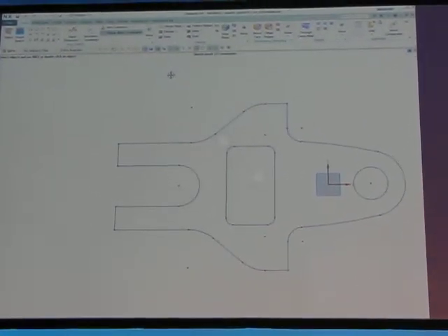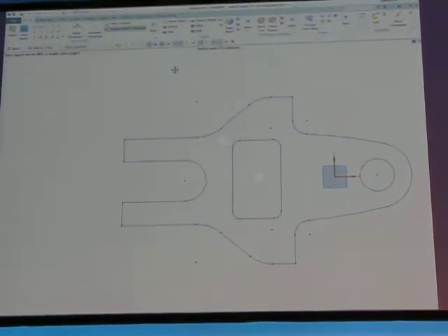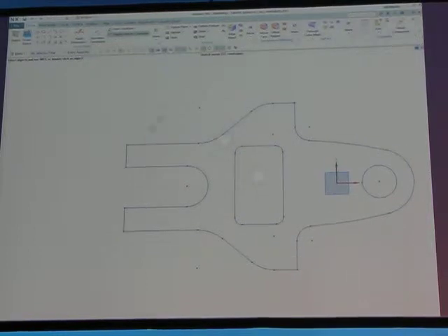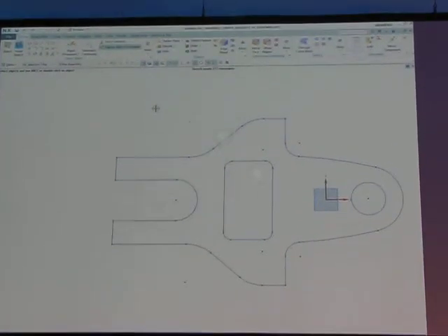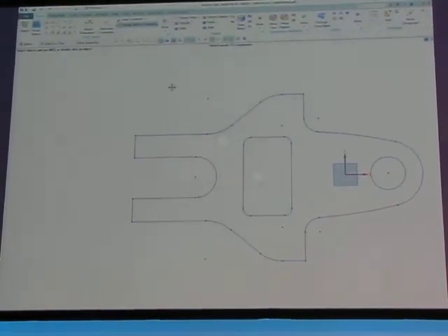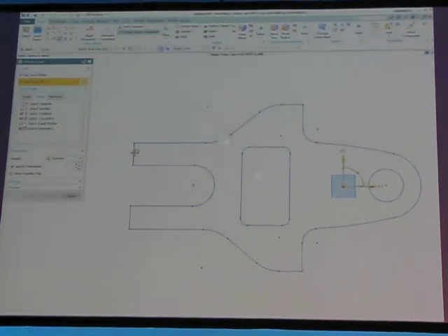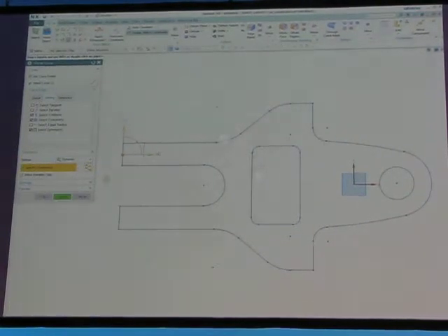So we thought, hang on, if we apply synchronous to this, can we solve the problem? What Paul's just done is gone backwards and taken out all the constraints, with a couple of undos. The system tells you it needs 233 constraints to solve this problem. Using a command now in NX9, synchronous in 2D, Paul can just do move curve, and in this case it's also found the symmetry, and he moves that over, it stays connected.